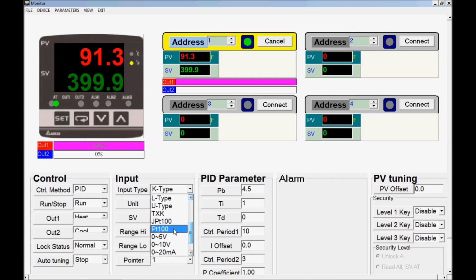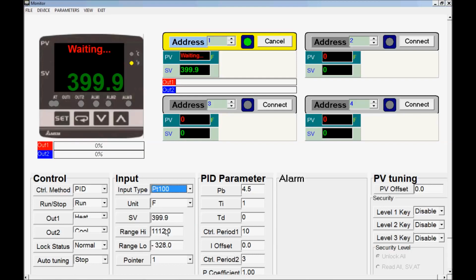When you have an out of the box temperature controller, you'll look up in here where it has PV, that's process variable, it says no connect. Well, that doesn't mean that you're not connected to the temperature controller, because you can see all this field here, so obviously you're connected and you're green here.